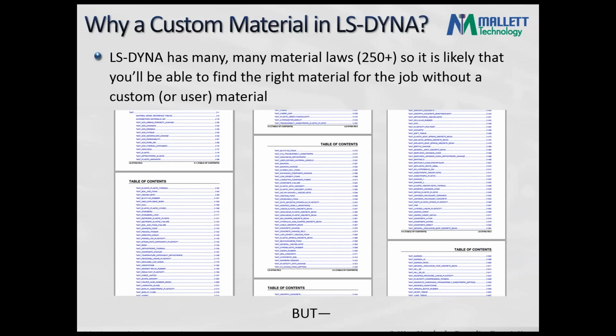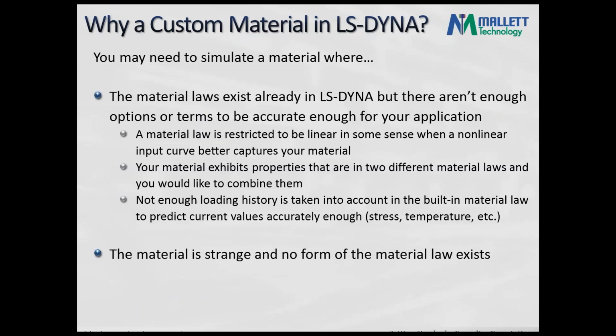So now that you've chosen to use ANSYS LS-Dyna, why would you have a custom material? LS-Dyna has a lot of materials, over 250. It surprised me, even after using it for so long, to see that number. So it's pretty likely that you'll be able to find the right material for the job without using a user material. But you may need to simulate a material where